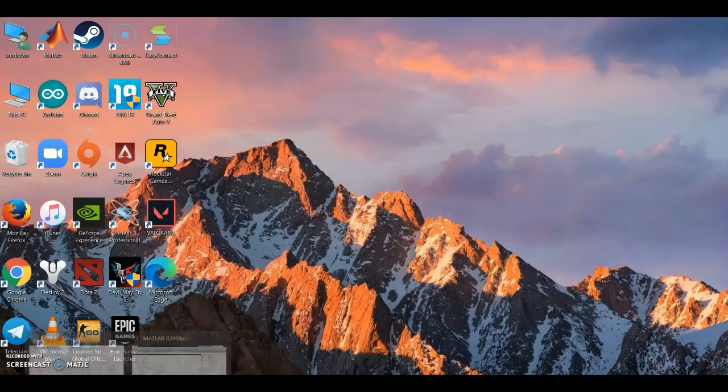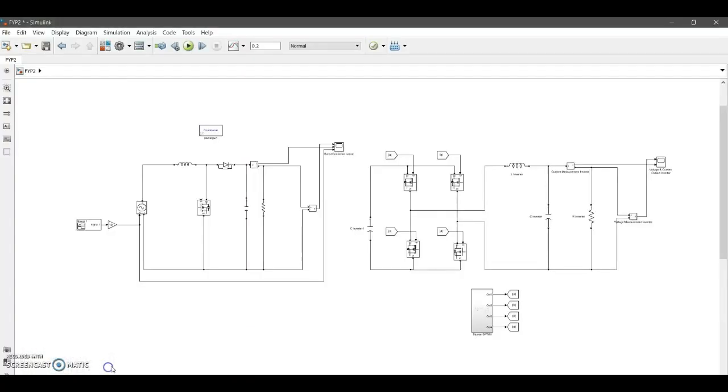I will be using MATLAB-Simulink for my final year project. My title is closed loop boost converter with SPWM inverter. For refreshing, in the last final year project, I discussed the open loop system, which is a boost converter and the SPWM inverter. The boost converter will constrain the output voltage and inject it to the SPWM inverter to see the total harmonic distortion, which should be below 5%.